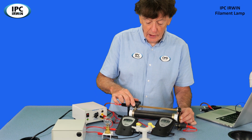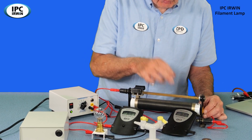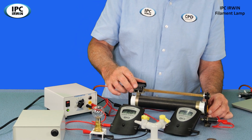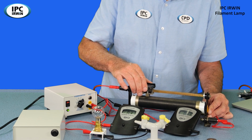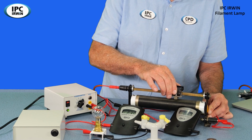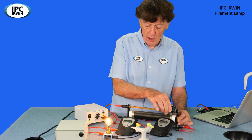So if we now adjust the slider, at its far end here, we've got 0 current going through the lamp and 0 volts across it. So we can actually get down to 0, 0 as our first measurement, and as we gradually increase this, we can get the full range of potential difference and corresponding current across the lamp like so.